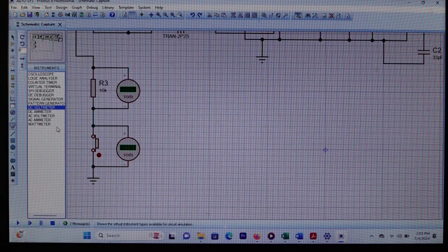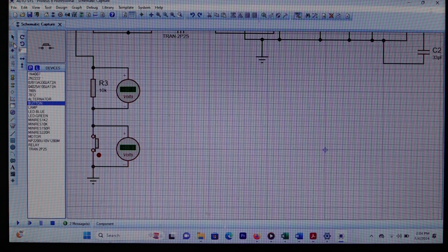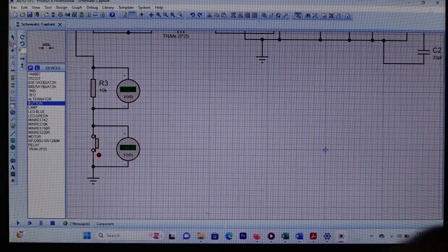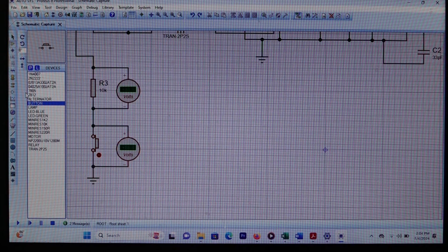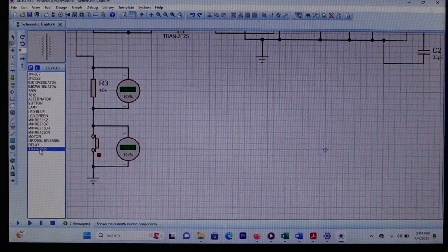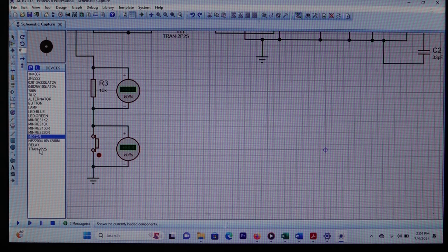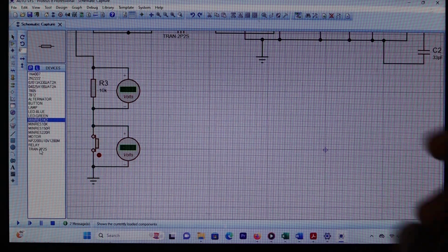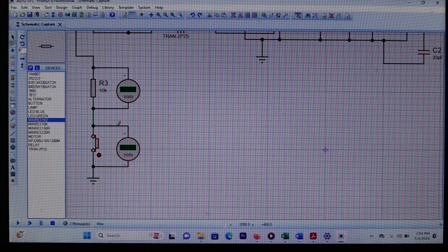Okay, so the next, the first block, it's the NPN bipolar junction transistor switch. We have to go back to the component mode, and then the first component that we need is what? Bias resistor or base resistor, right? So the value of the base resistor that we learned theoretically is 1.2 kilo ohm. So 1.2, I say that this is the object selector, working together with the object preview window.